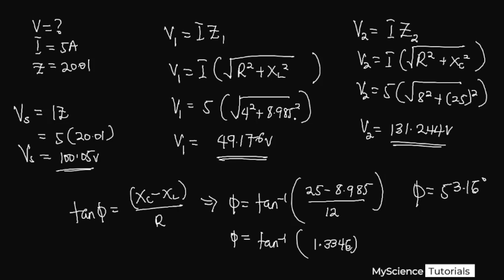We look at the various impedances that we have. If we have a resistor common to them, we add them the way we add resistors in series and then write our total. Redraw the new circuit and write the total resistance. If we have inductance that is common, we add all the inductances and then have our total inductance. If a capacitor is present, 1 over C total is equal to 1 over C1 plus 1 over C2, till the number of capacitors you have. You add that and get your total capacitance, and then from there you can go ahead and use these values to calculate your total impedance and go ahead to find any other problem that the question might demand from you.